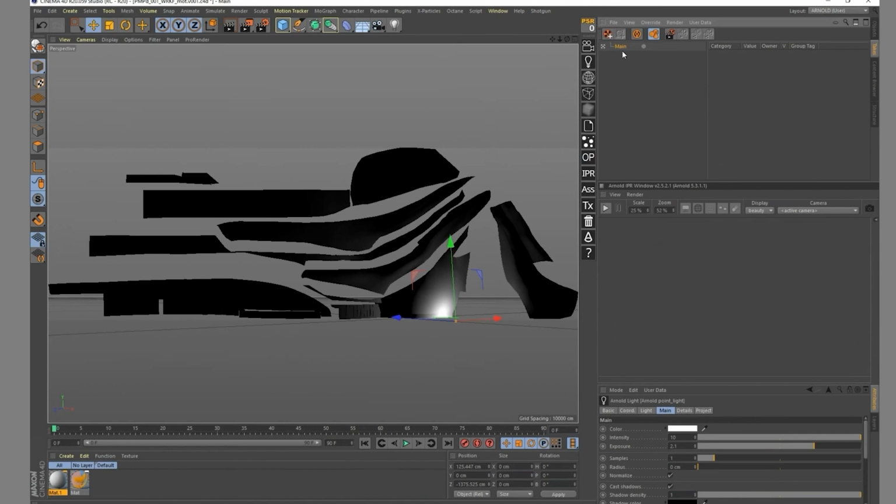Everything that you do, you need to be doing it on the main take, and then you can create a new child take that I'm gonna call F for full. And to that child take, I'm gonna assign the full res render setting. I'm gonna do the same with everything else, naming something H for half res, and naming something Q for quarter res.